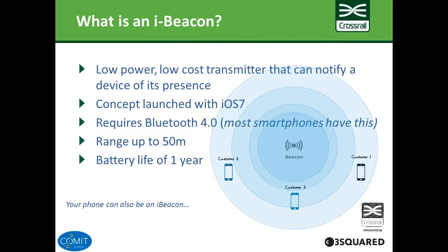The most obvious example in my career was in highways work, segregating live moving traffic from the operatives who were working on the road itself. We tried a number of different techniques back then, 8 years ago. We partnered with a company called UBSense, who use ultra-wideband sensors, mounted on telegraph poles around the site. We could model the site in 3D, we could put sensors in people's hard hats, and we could monitor people as they moved around the site. So technically it was a success.